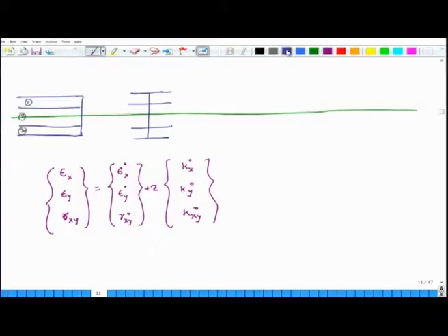So, along this line AD, the value of x and the value of y do not change. The only thing along line AD that is changing is the coordinate z. x and y are not changing, which means this function does not change. There is no change in this function because x is fixed and y is fixed. So, mid plane strains are fixed.